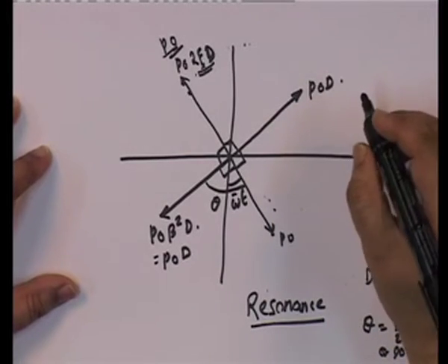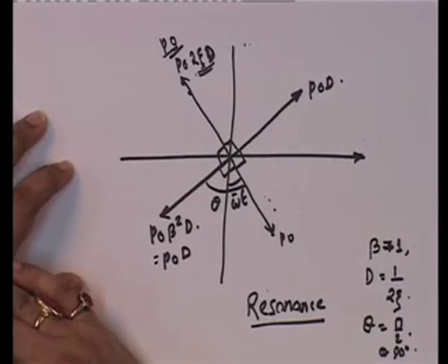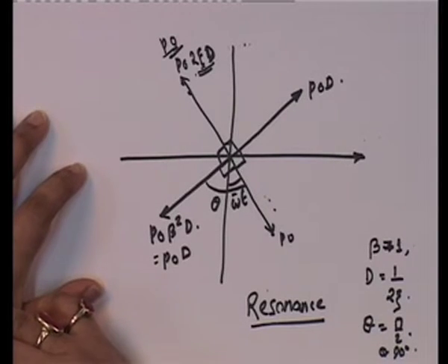So you have a peculiar situation at resonance: since the damping force resists the applied load, the inertial force and the elastic force are very large. However, they are 90 degrees out of phase with the applied load. So, despite being very large, all they do is cancel each other out.